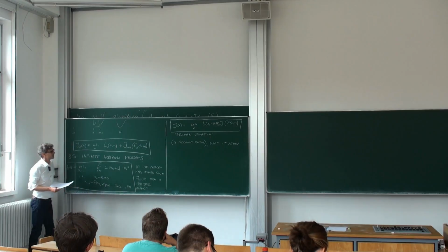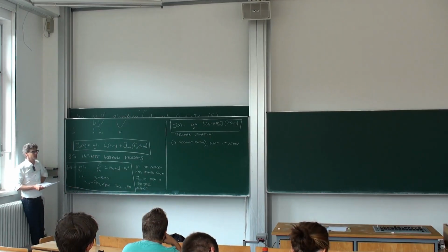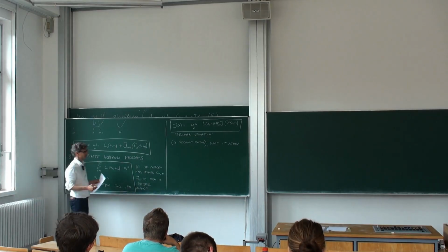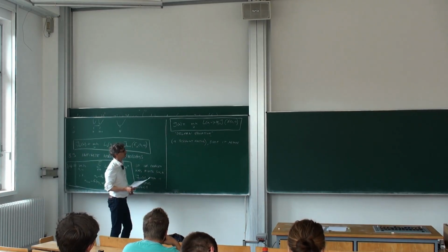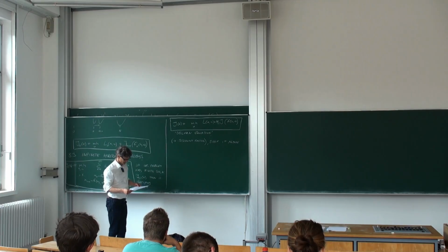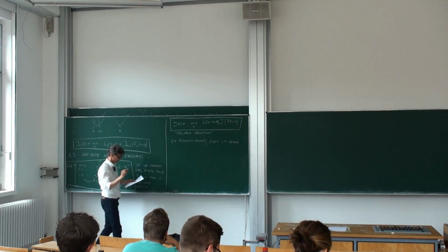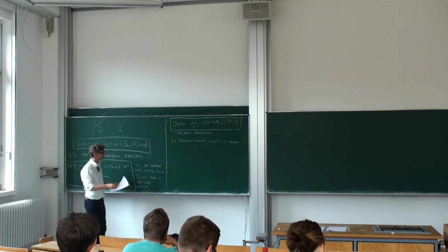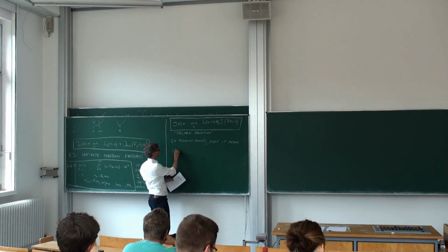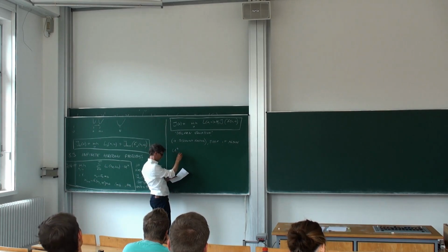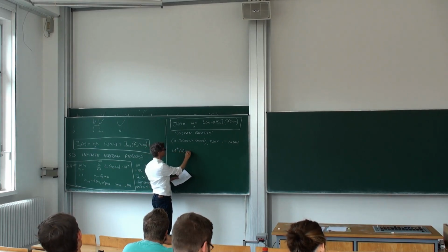So now this Bellman equation can be solved in some cases. Of course, you can try to solve it in a discrete state space. But you can also solve it for the linear quadratic regulator, and we will do that in a minute. But before we do that, I want to make a few things and define them. So the question, what is the optimal control here, is also now without an index.